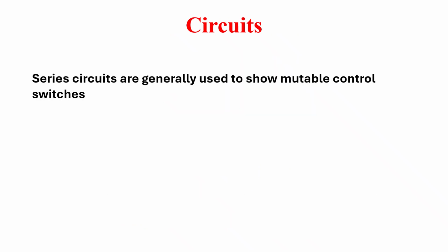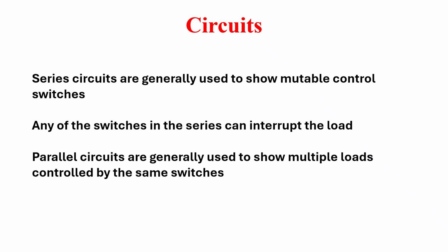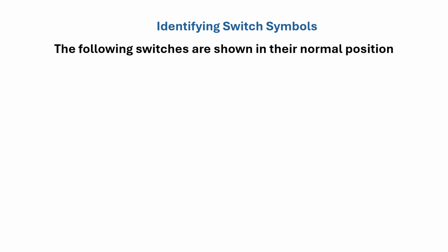Series circuits are generally used to show multiple control switches. Any of the switches in the series can interrupt the load. Parallel circuits are generally used to show multiple loads controlled by the same switches. The following switches are shown in their normal position.